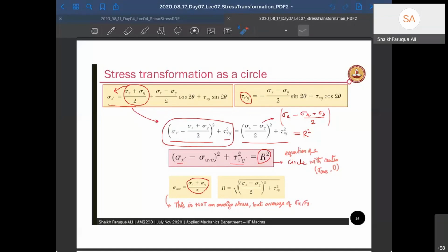So one of the directions will give the other three directions, right? And the value for one will give the other three values. So all these shear stresses can be known from only one shear stress. And we also understood that stress can be represented by a 2 by 2 matrix for a two-dimensional system, or two-dimensional planar bodies.